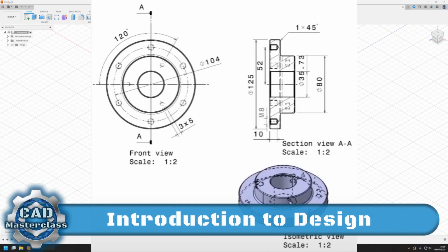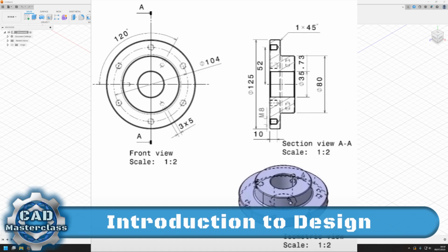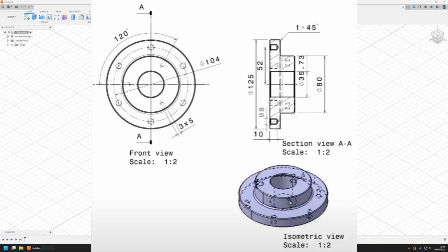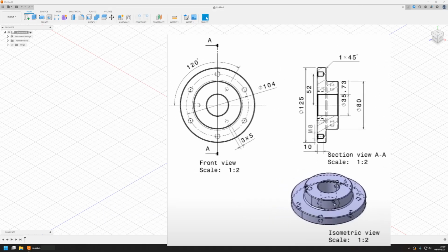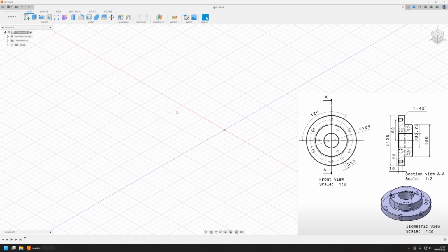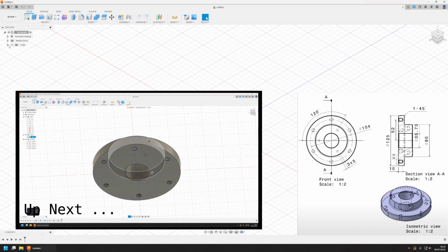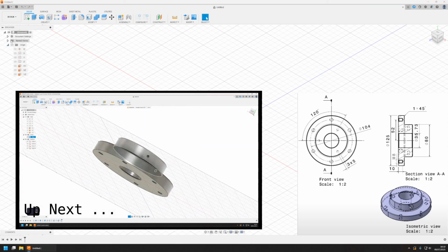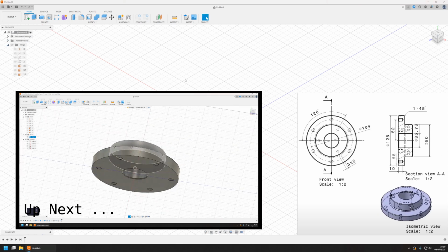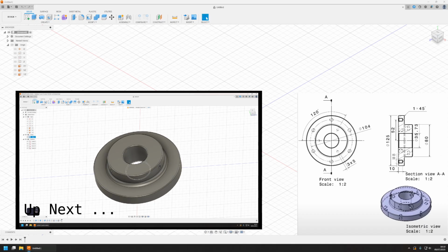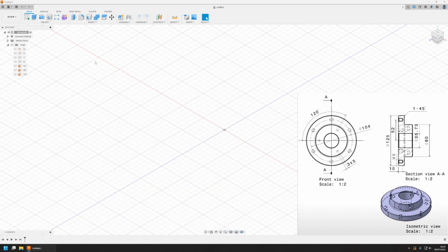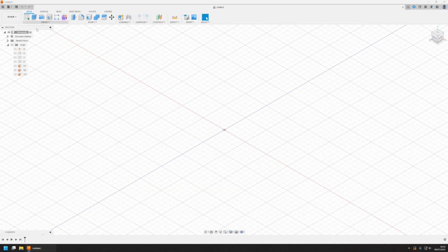I will start with this part, which I've also used in my CATIA tutorial series, because I believe it's gonna be a great start. Okay, so we have this part here that looks maybe like a lid or flange or something, and we notice that it's going to be basically 2 cylinders stacked on top of each other, 2 very short cylinders. So to do that, we're gonna generally start by drawing a sketch, and then we're gonna extrude that up in the other direction.